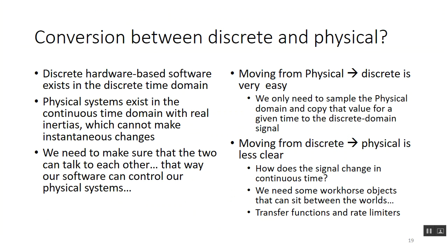So what we're struggling with here is the difference in sampling time and notions between discrete, or something that can change instantaneously, and a physical system where it has some kind of inertia, some kind of finite energy transition time. Energy just doesn't go from here to here, whereas in software, the variable x is now 2, and at this instant it's 3, and it looks like a step function. And ultimately, for our project, we've got to connect these two dots, because we're going to be telling it, go to this elevation, go to this bearing, and there's going to be a hydraulic system saying, hey, wait, I can't move that fast.